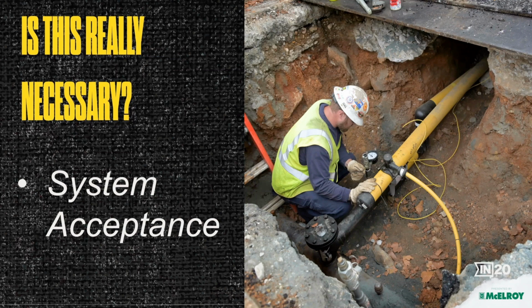Post-construction testing prior to burial or turning the system on is the primary method used for system acceptance in the industry today. We hear it all the time, especially in cases where something has maybe been called into question. Did it pass the pressure test? That's the question that gets asked. And the answer to that question is often used to make a decision that could have a major impact to the installer, the owner, or any other parties involved. It does carry a lot of weight.